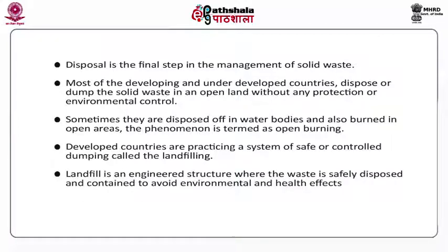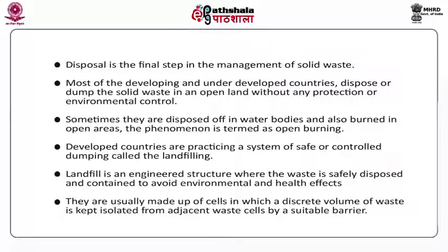Now, as I told you, landfill is an engineered structure where the waste is safely disposed or contained to avoid environmental and health effects. They are usually made up of cells where discrete volume of waste is kept in isolation from each cell. What I mean to say is the landfill is divided into imaginary cells where the waste is loaded and separated from the adjacent cells by a suitable barrier.